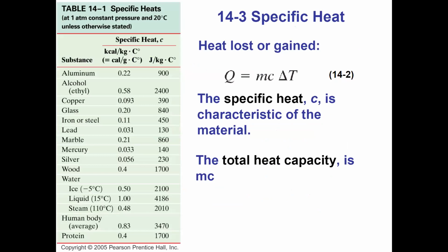Now, when we add energy to a system, if it has lots of ways of storing energy, then the temperature is not going to increase as fast. This leads us to the concept that, depending on the material, the proportion of temperature increase to how much heat is added will be different.